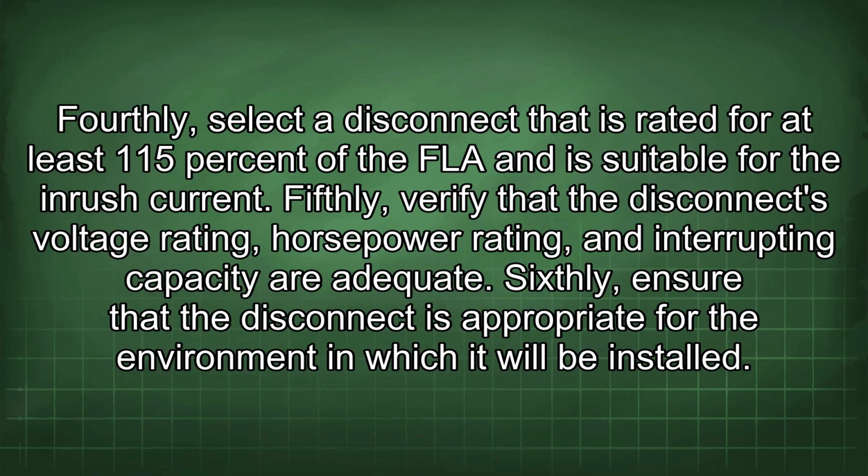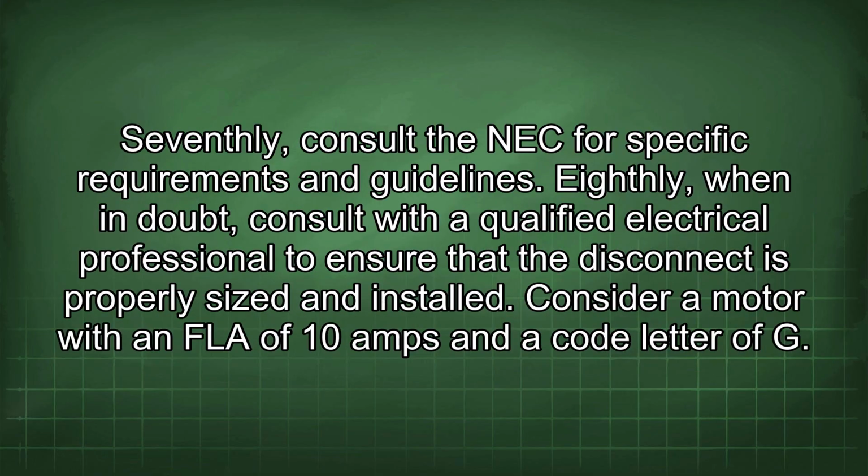Fifthly, verify that the disconnect's voltage rating, horsepower rating, and interrupting capacity are adequate. Sixthly, ensure that the disconnect is appropriate for the environment in which it will be installed. Seventhly, consult the NEC for specific requirements and guidelines. Eighthly, when in doubt, consult with a qualified electrical professional to ensure that the disconnect is properly sized and installed.